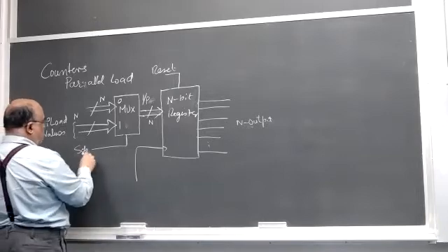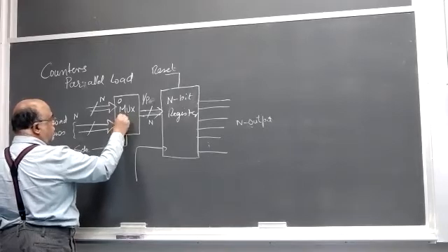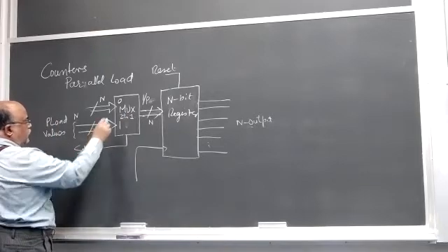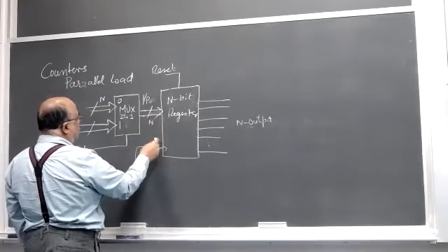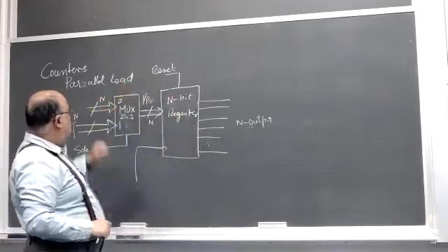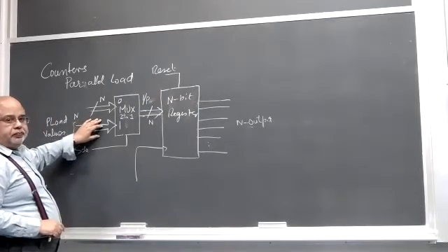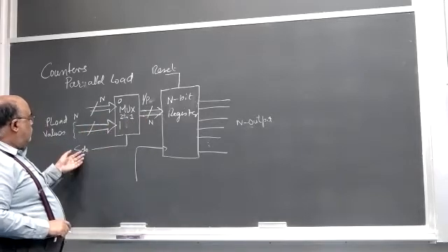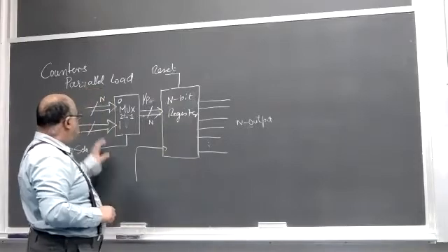Basically, this is a 2 to 1 mux. When you make it 0, this value is presented over here, and depending on up count and down count, it does the normal stuff, counting up, counting down. But when the select line is 1, this parallel load plays its part. So this value is presented over here, and when the clock comes, the counter is loaded with this value.